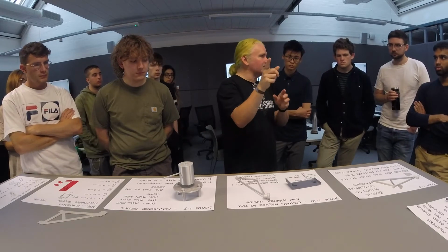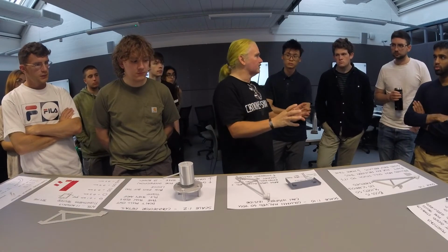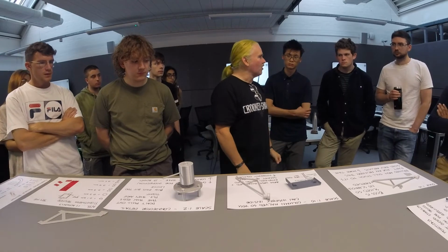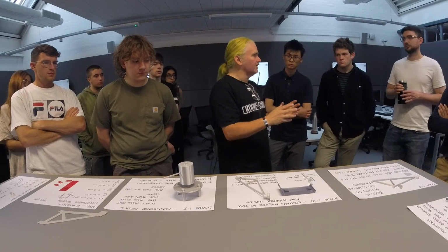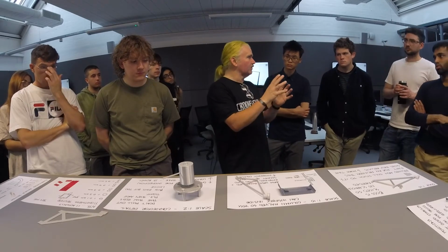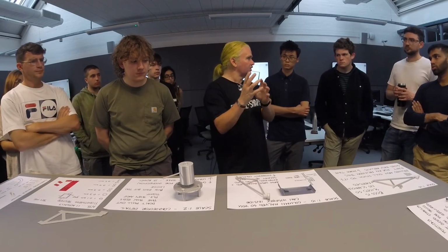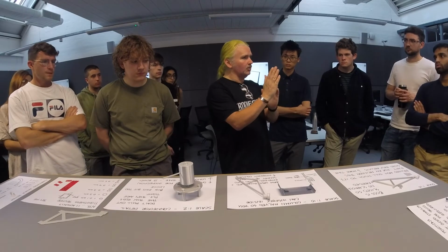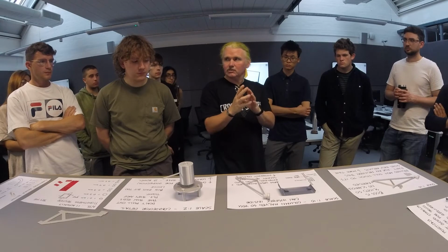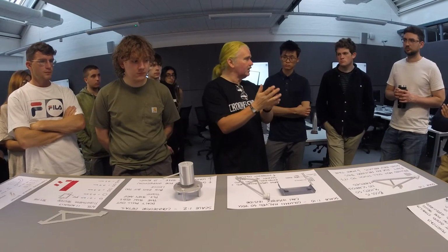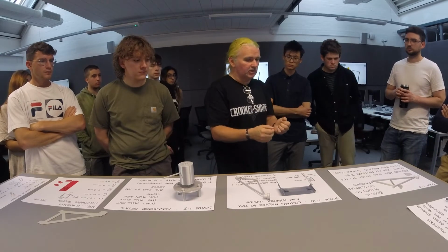But every time I took it into the slicer, loads of scaffolding. What am I doing wrong? I twigged that it's not just about the overhangs, it's about the overall stability of the shape. If that shape wants to fall over, then the scaffolding's needed. So it was putting it in for stability, not just for dealing with the overhangs.